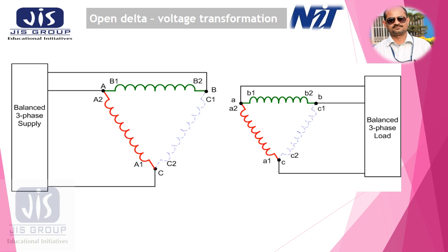Okay, now out of the three transformers used, phases A, B, C, the transformer of phase C got damaged and has been removed, so that in this delta connection, both in the primary and secondary, the coils to be connected between terminals capital C1 and C2 for primary and small for secondary are absent.